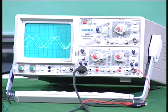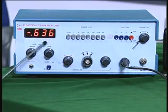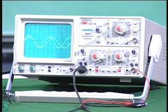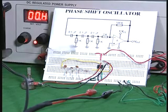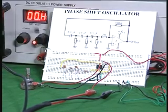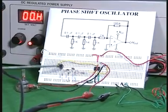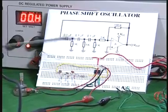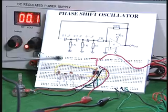So you see when it is coinciding, there is a continuous phase factor which is coming, that is why it keeps on moving. If you arrest them both, you would find the frequency is almost the same. So it is around 636, that is what you see here. This is the frequency, and if you actually calculate 1 by 2 pi RC with R 1 kilo ohm and C 0.1 microfarad, you will get close to 600 hertz. But you may not get the exact value, and that is because there is also a tolerance of these resistors and the capacitors. You all know that. Because of that you will not get an exact value, but you should get a very close value corresponding to 600 hertz.